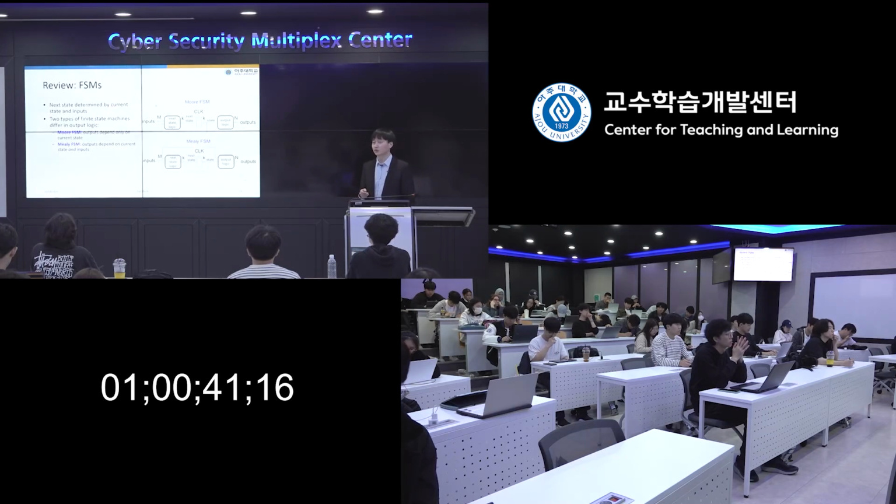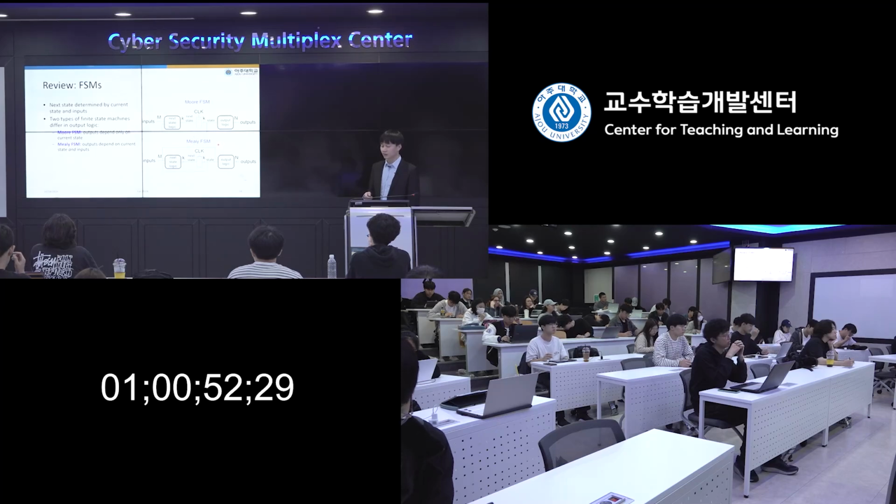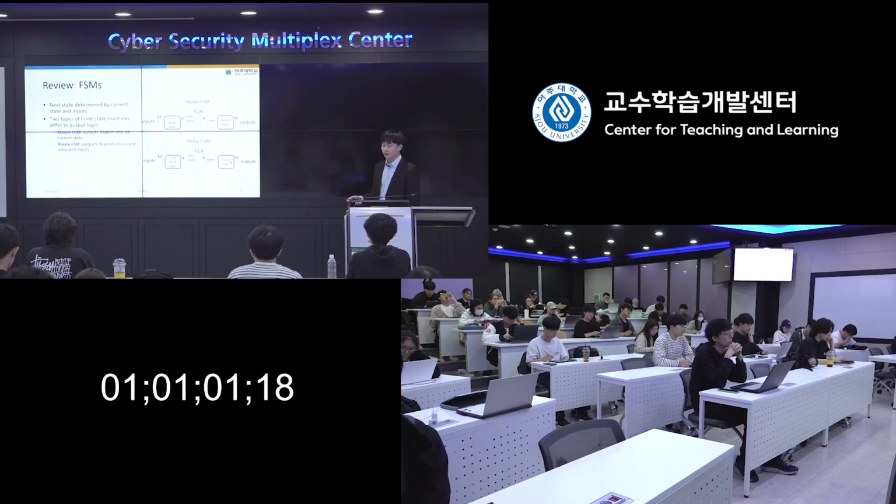Okay, so now we move to another topic. So far, we have been checking this Moore FSM, the design procedure following the Moore FSM. Actually, we have also another design principle called Mealy FSM. The difference is that the Mealy FSM output logic receives both the current state and the input. The output logic will be decided by both the current state and the input. The input could be the sensor information or clock, any other information.